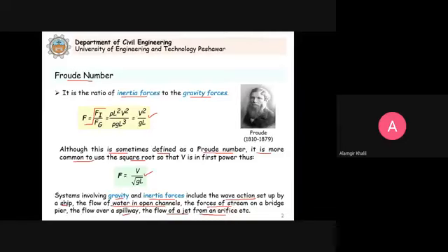If instead you consider the Reynolds number for dynamic similarity, then the results will not be accurate. That's why basic knowledge of fluid mechanics is very important before we apply these concepts. You must understand the phenomena very well in order to analyze the problem, because there are so many dimensionless numbers.